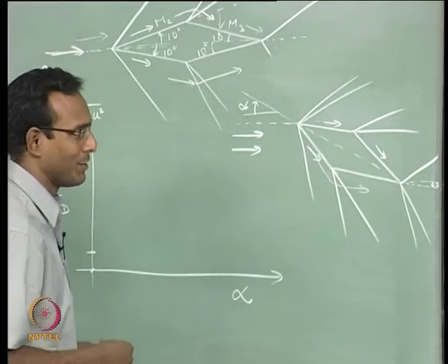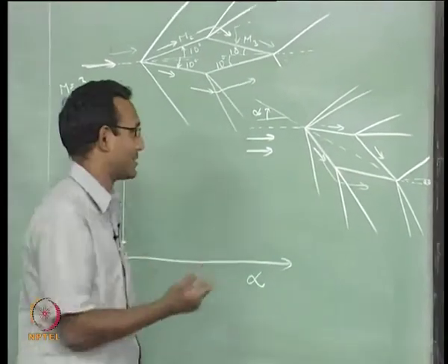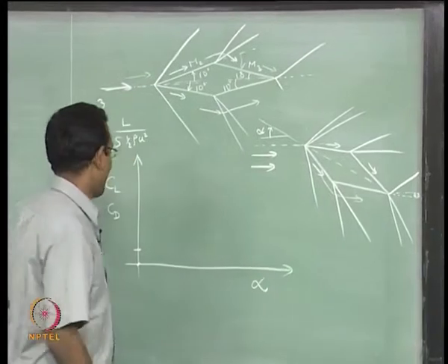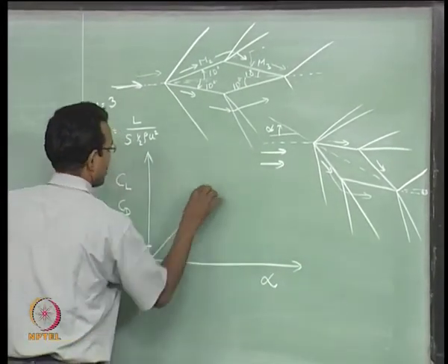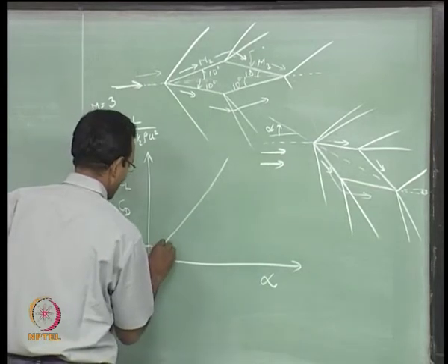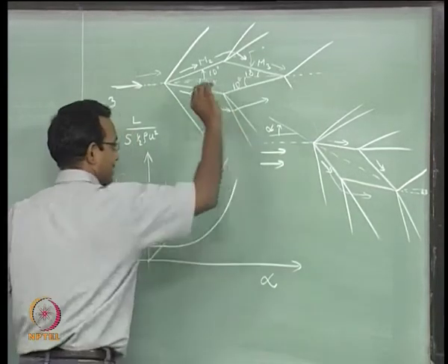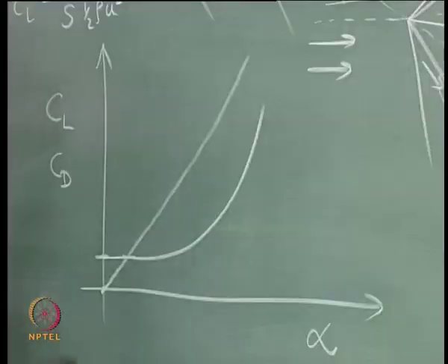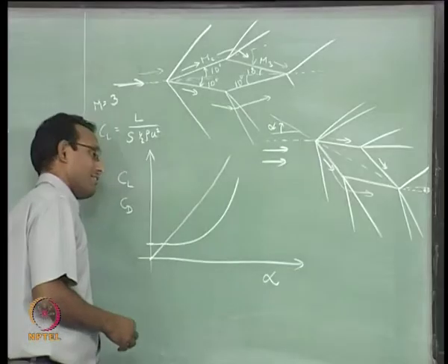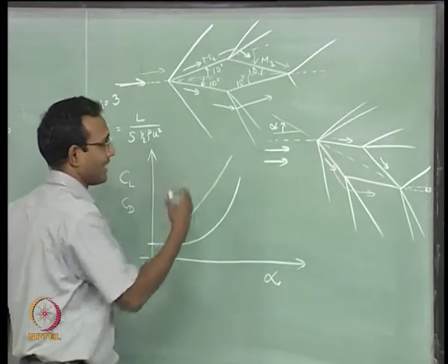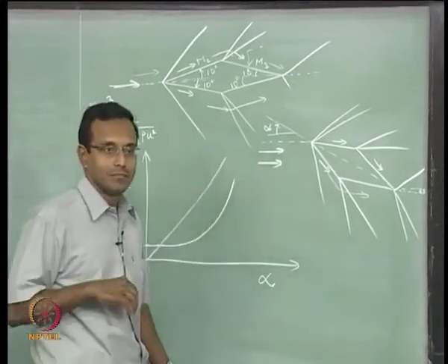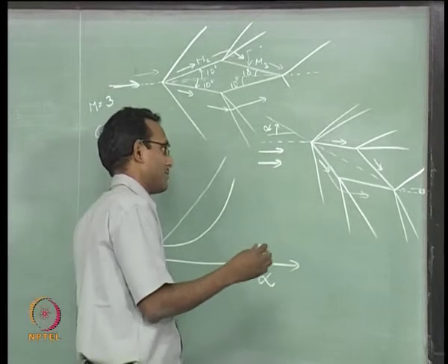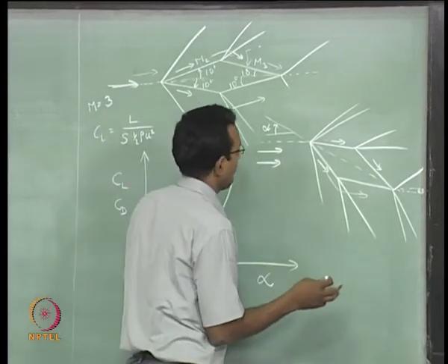I would say I am going to give you exercise on the web where you can solve this whole problem. If you look at what it does, lift is going to increase slowly while drag is going to start slow but increase drastically. This is what will happen. Okay. I will show you actual data for this 10-degree angle with Mach, I think it is Mach 2. I have a plot of that, we will show you after some time.